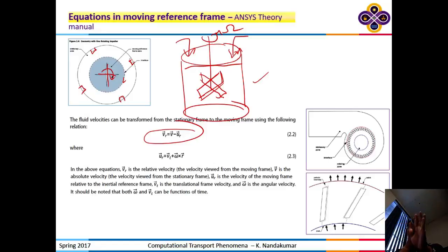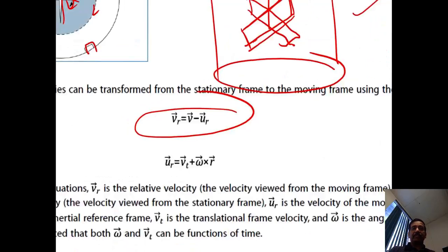But you know physically that the velocity should be the same, unique, right? So you impose the condition by smoothing things at the interface. So it introduces some sort of an interpolation error at the interface. Okay, that you can control by controlling the grid size and the time step. If your time step is large, then the moving reference frame can move a lot of distance in one delta t, and then matching the velocities would be more difficult. So typically the multiple moving reference frame idea will require you to use a smaller time step size, meaning the computational effort will be larger.